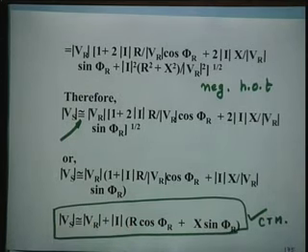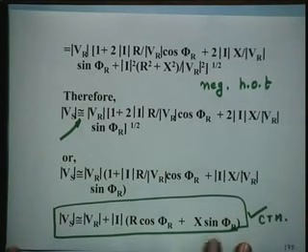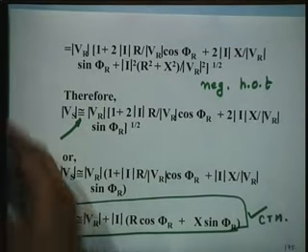So, we have derived it using a phasor diagram, using mathematics, Pythagoras theorem, Taylor series expansion, in fact we have used, and ignoring higher order terms. Finally, we have got this equation. So, this equation is very important. The diagram I have just now shown you is a phasor diagram of a short line